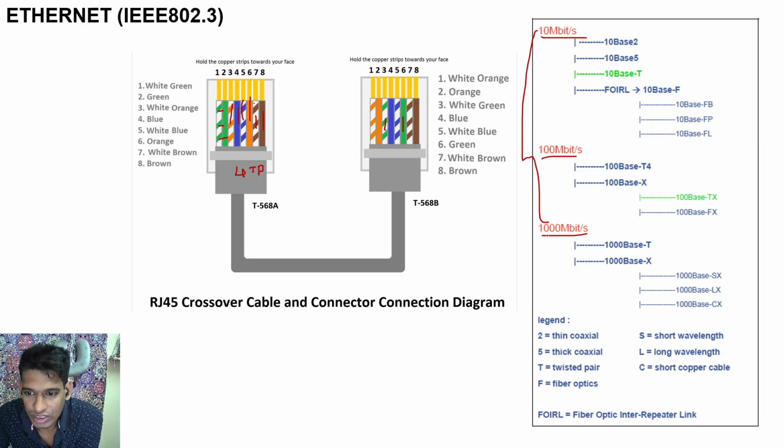It will try first for a 1000 Mbps connection. If it fails, it falls back to 100 Mbps. If it fails, it falls back to the legacy 10 Mbps connection. So even if you crimp only these two pairs correctly, you might think you have an Ethernet connection. You might ping the relay and say, okay, it is getting pinged. But that might be following a legacy system.